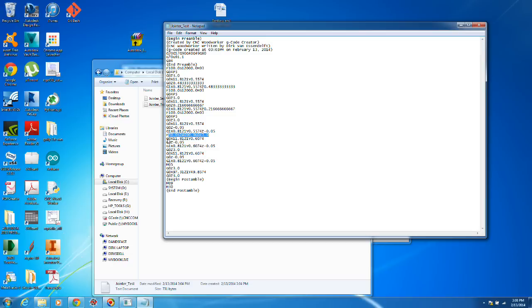final pass, and again it goes to the 11.5 and down to the maximum Z and maximum plunge depth, and then does the travel to 0, again up and back and down and across, and then turns the spindle off, goes up to the safe Z height, and traverses down to the end of my table so that it's out of the way.